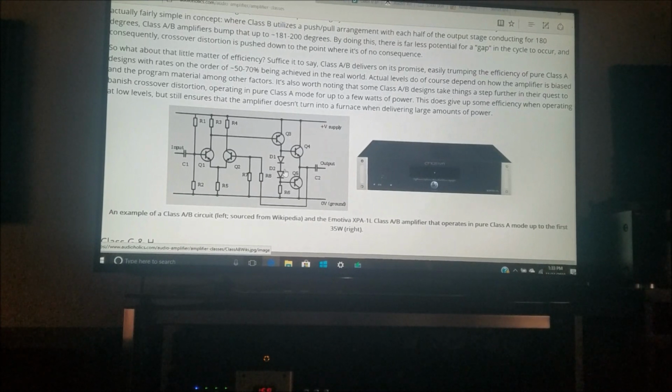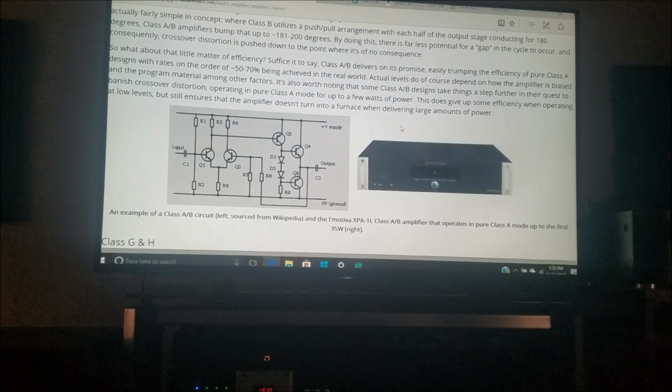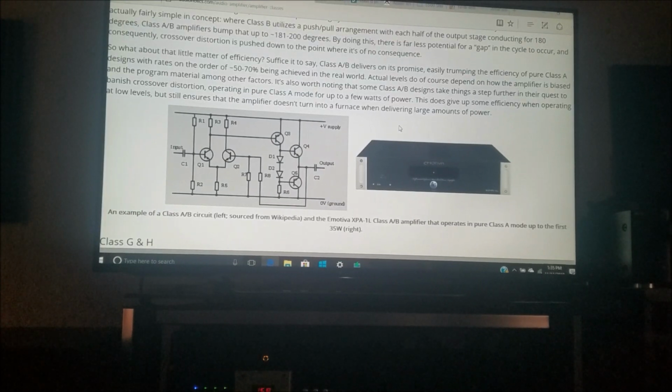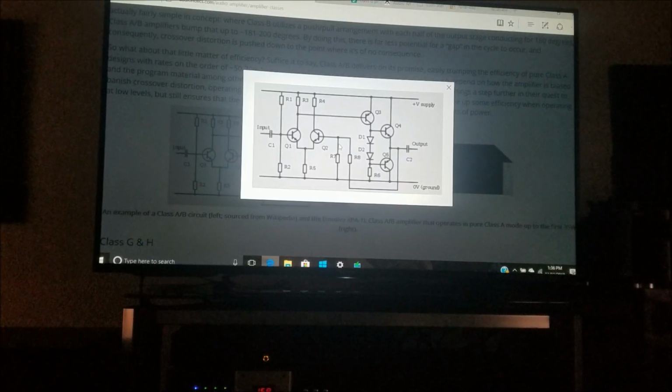Now, technically, in the engineering world, it's been said that the exact choice of quiescent current, that's the standing current through both devices when there's no signal, can really make a big difference to the level of distortion and to thermal breakdown that causes devices to shut down. And ultimately, there's a bias voltage applied to set the quiescent current, and that's adjusted by the temperature of the output transistors. You know, in fact, it wasn't until a few years ago that I really cared to know as much as I can about this.